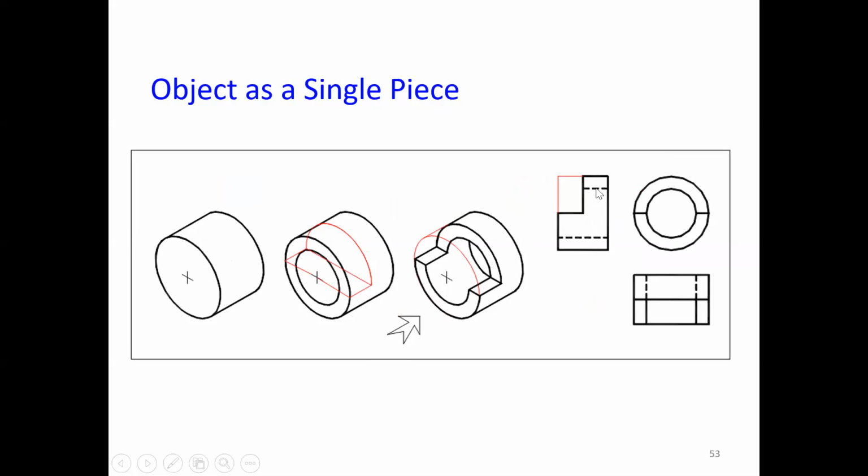So here what we have to do, suppose you see from the front, you will get the 2 circles, but one step is there. So one line is visible here, one line is visible here, so that you can draw it here. But if you see from the top, one rectangle for this, then these 2 rectangles, one rectangle is here, these 2 rectangles, and this one rectangle. Getting? But the inner circle, whatever there, that is hidden here. So that's why it is required to draw it by hidden lines.